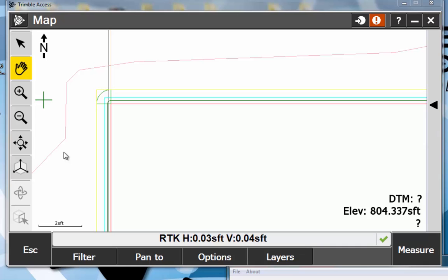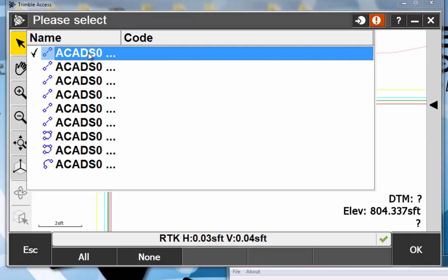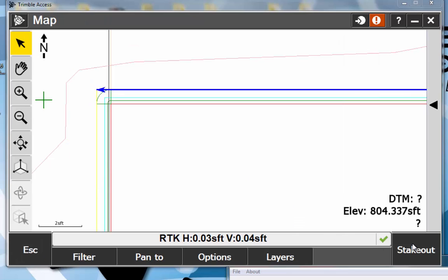All right, so here's my back of curb line. It might be kind of hard to see with the display here, but notice what happens. I think this is a layer I have to turn off. We'll see. Notice what happens though. My point is, when we export a DXF and we have this line work, and I stake this back of curb in a DXF, the advantage is it's easy, right? It's an easy export. It's an easy thing to load.